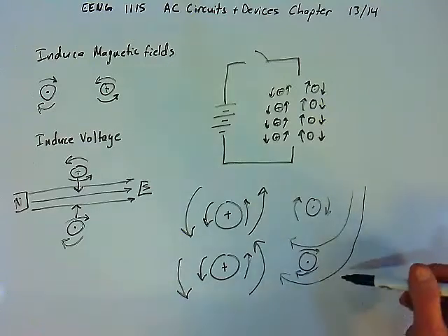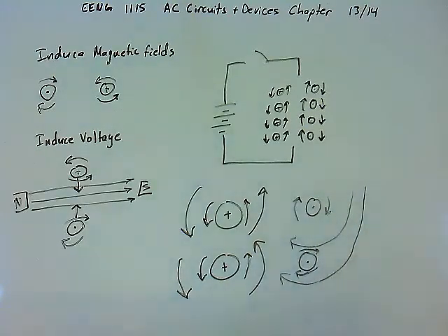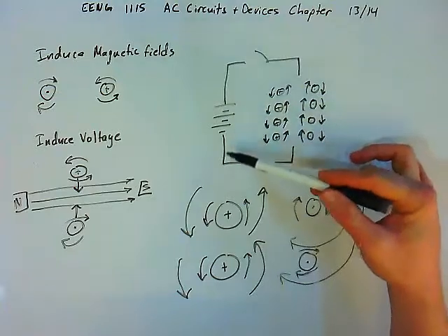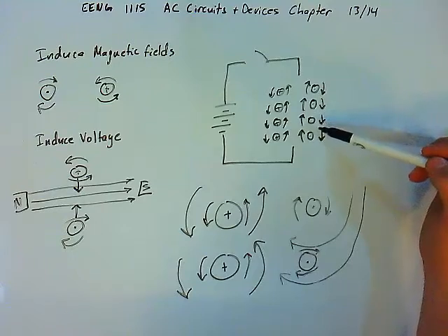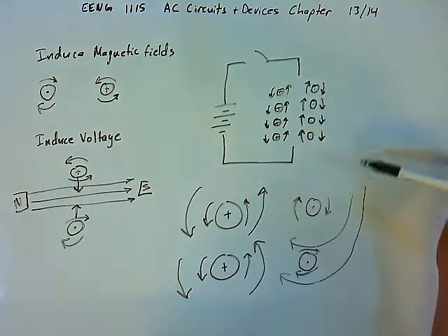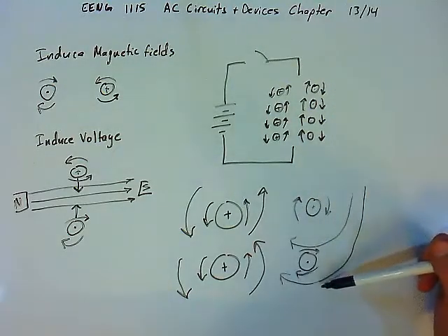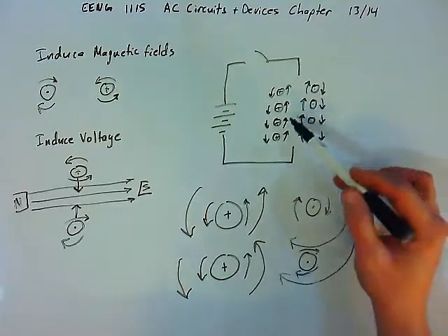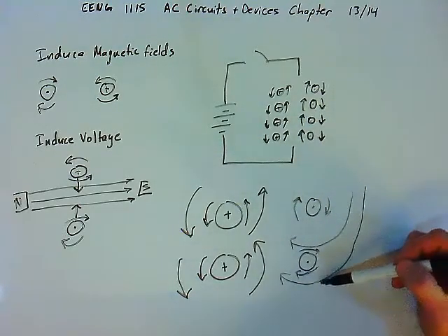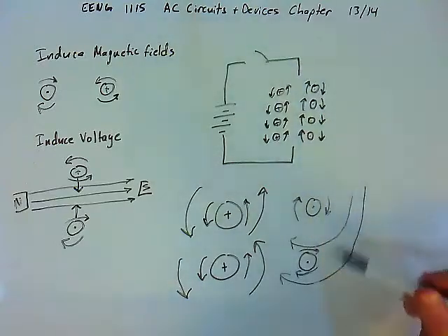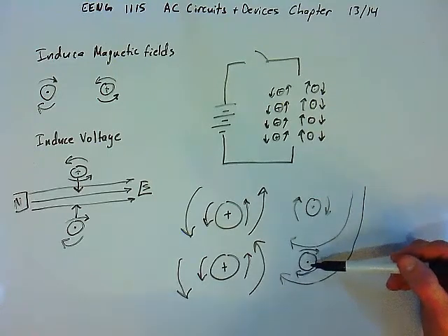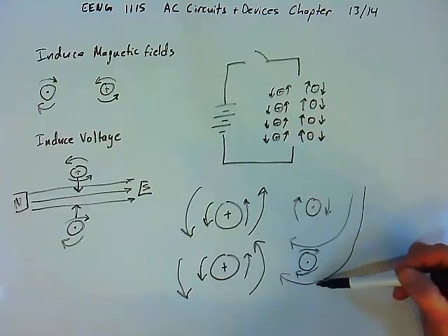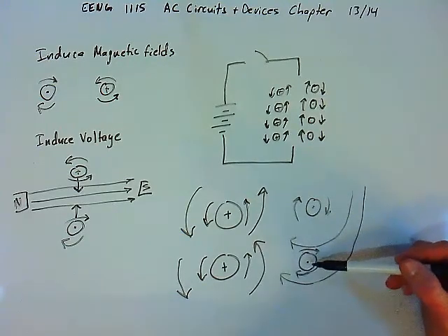And so this is a very interesting property of inductors. Remember that an inductor resists the change in current. So when the current started off as 0 and we closed the switch, the current wanted to increase, but the flux lines growing was slowing that change of current. The current could not change instantaneously. When we reopen the switch and the magnetic field lines collapse, the current in the inductor was already at some maximum value. When the flux lines are collapsing, because the switch was opened, they're cutting the neighbors in such a way that the current, being at a maximum value, wants to remain at a maximum value. The collapsing magnetic field lines are trying to keep the current flowing in the inductor.